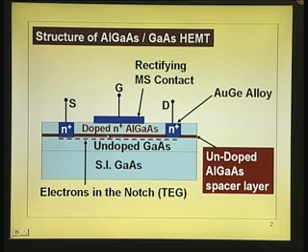But in this case, you have a doped layer, and that doped layer actually should not be conducting. It should be depleted totally, otherwise current will flow through this. So, in a way it is more like a MESFET as far as the top layer is concerned, and a MOSFET as far as the interaction between the gate and the channel is concerned. Because between the gate and the channel, in the MOSFET you have got the oxide. In the case of the high electron mobility transistor, you have got a depleted region, which acts as an insulator.